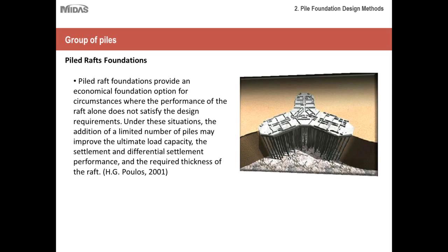So as you can read from the slide, piled raft foundations provide an economical foundation option for circumstances where the performance of the raft alone doesn't satisfy the design requirements. Under these situations, the addition of a limited number of piles may improve the ultimate load capacity, the settlement and differential settlement, and the required thickness of the raft.